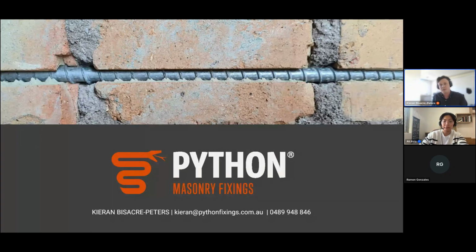Horizontal, they can be installed at angles, not a problem at all. Of course, if you are installing them at an angle, you're introducing combined actions, tension and shear, and so you will need to account for that by calculating the reduction in strength, and typically that's limited to 1 in masonry for the combined actions check. But certainly, particularly with steel applications, for example connecting through the flanges of big UCs and UBs, Pythons will often be put in at an angle, so it's definitely something that's done all the time. And 100%, we have capacity tables. We've got a mountain of data for all of our fixings and every relevant Australian substrate you can think of, so more than happy to share that with you afterwards as well.